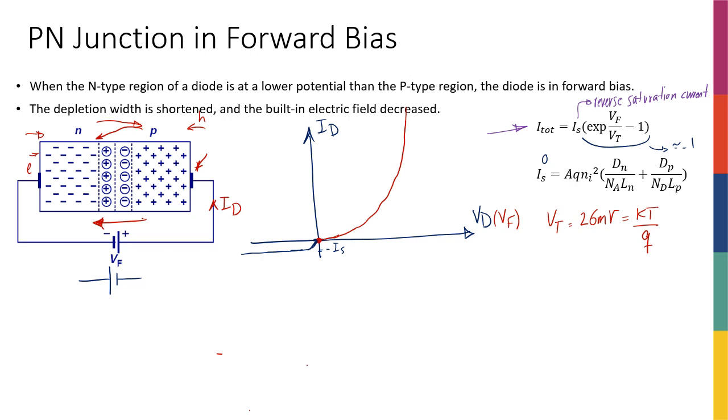That's why we even call the reverse bias diode a capacitor, because we know there's no current passing through a capacitor, right? But it is a very small amount of current, and it is in the reverse direction of the normal diode current, right? Normally the diode current is always from the P side to the N side, but since this current is from the N side to the P side, we call it the reverse current. And since it saturates very quickly, it's almost always at its saturation value, we call it reverse saturation current, or IS.